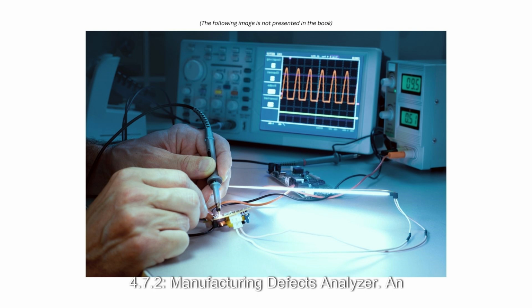4.7.2. Manufacturing Defects Analyzer. An MDA, Manufacturing Defects Analyzer, also uses the flying probe approach. The MDA does a subset of what ICT can do, but was specifically designed to increase test throughput. Its primary purpose is to catch manufacturing defects, such as pin leads not making contact to the board, or any other non-continuity condition.